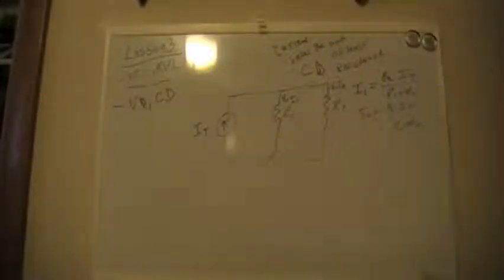Voltage division, we had the same resistor, V1 R1, V2 R2. For this, it's I1 R2, I2 R1. So it's important that you guys make sure you remember that. The easiest way for me to remember stuff like this is that current takes the path of least resistance, or most of the current will take the path of least resistance. Charge is going to want to go the direction that it's met with the least amount of opposition. If it's met with a ton of opposition, then it's going to take the path that doesn't have as much opposition. So that's how current works and how it flows.